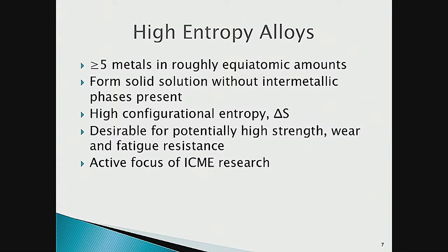Now this as a whole, to be additionally a high entropy alloy, must form a very solid solution type matrix without a variety of intermetallic phases. This leads to a high configurational entropy and hence the name high entropy alloys. There should be a little caveat in there, that there's some variation in the definition of high entropy alloys, but this is a generally accepted one.